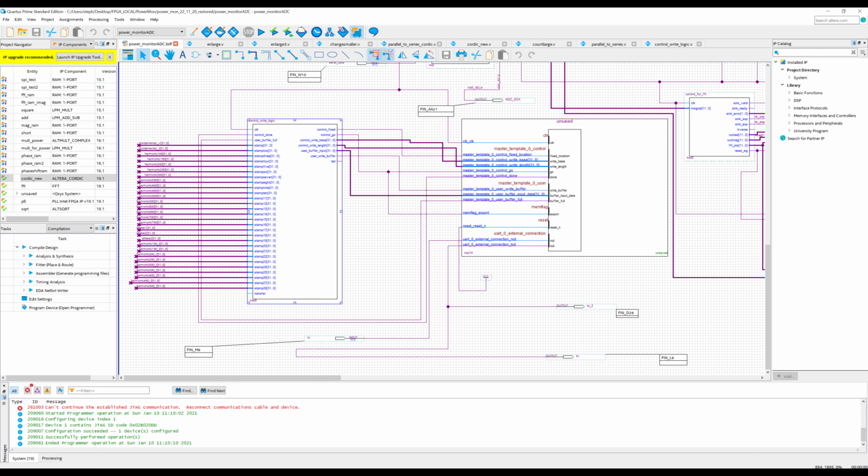We've got the UART transmit pin here, and that's going to this pin and this pin. So it's actually going to 2 pins. One of these pins is associated with the serial connector on the Cyclone 5 board, and one of them is just a pin. So what I've done is I've connected a USB cable from the USB port on the Cyclone 5 starter kit, and that's going into my laptop. That's what the Matlab graphical user interface will connect to, and hopefully pick off those UART characters as they come in and then plot them in a graphical user interface.